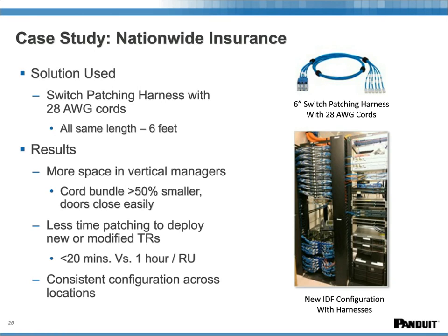And he is doing, let's refer to one-to-one in this case as simply dedicated port assignment, going from a particular port on the switch to a particular port on a panel. At Nationwide, there's a systematic approach used for the labeling of each panel using letters. So A, B, C, D for a 4-line card installation, or longer if it's an 8 or a 6, depending on the size of the TR.